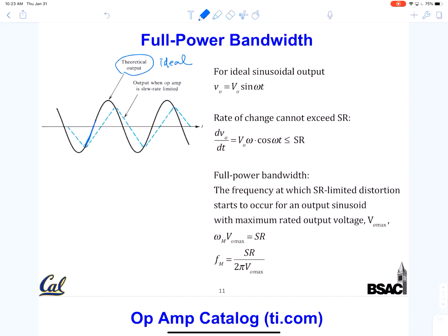So you chug along at your slew rate until you reach the desired output, but the input has already changed direction and is coming down at a faster slope than your slew rate. So you just turn around and go backwards, and you end up with a triangular wave. This is the extreme case, where your maximum slope is greater than the slew rate. If they are comparable, you get a partial distortion, not exactly a triangular wave.